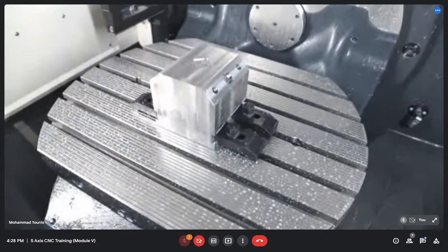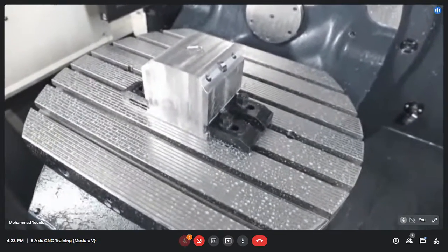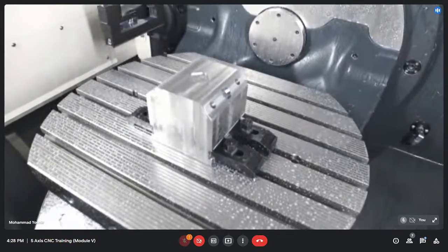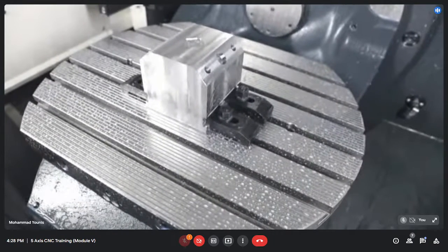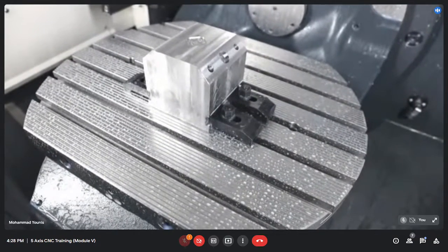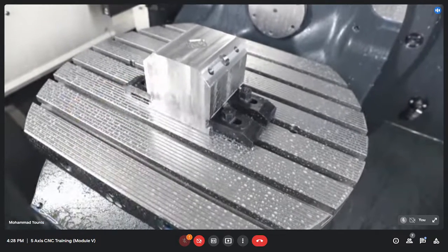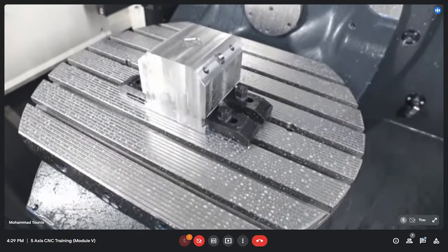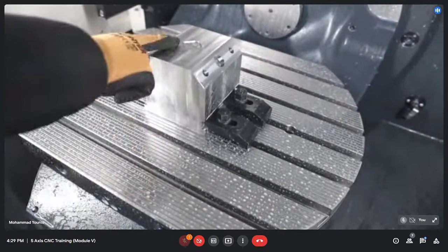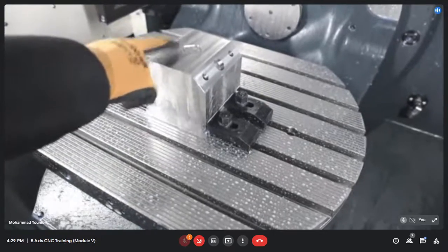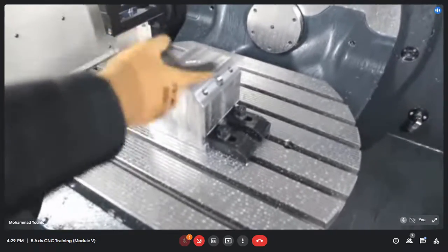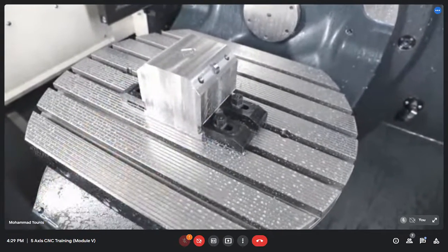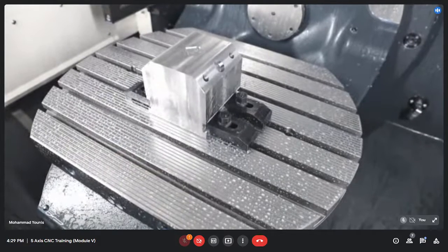So here, to make it simple, we have done these programs, these operations on this chamfer, but we can do any operation. Like we already have machined this spigot, sorry, this pocket here. We can perform any machining at any part of this surface at any angle with accuracy and precision.